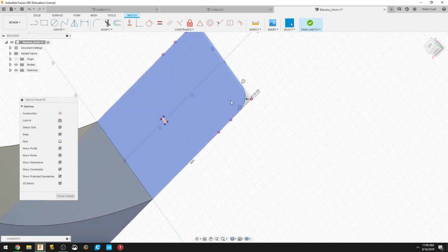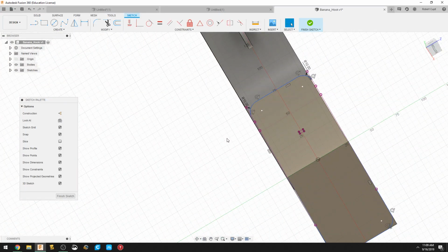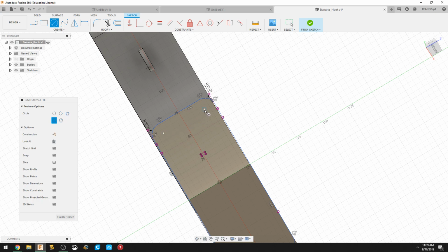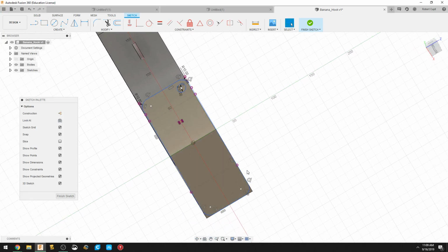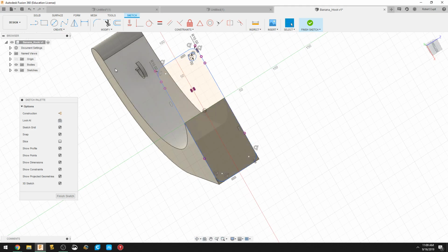When you make a fillet, it automatically makes these dots for the center of that circle, because all radius is a circle that's cut away some parts. So if you look at this, it says to make one circle that is 10 millimeters from one of these dots. It doesn't matter which one you pick. I'll do 10, Enter. Now you could make a whole other 3 circles, or you could do what they're asking you to do and go to Create.